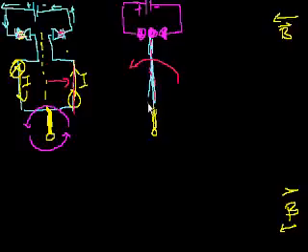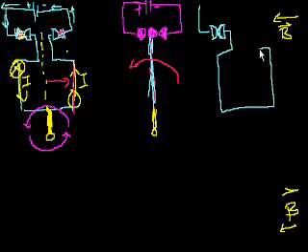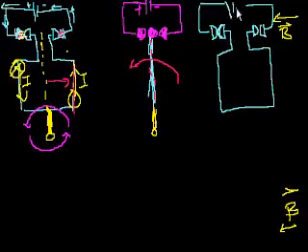and you just let a little bit of the angular momentum carry this whole rotating contraption further a little bit, to the point that your configuration will look like this. I know I keep changing colors, but the whole contraption will now look like this. Okay, that's my positive, negative, positive, negative. Current flows like this. Now, we assume that the commutator has gotten back in touch.